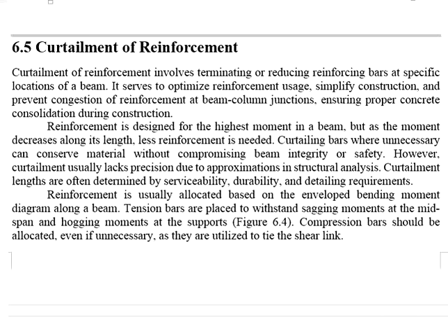Also, you need to know that the curtailment is not a really precise process, which is inherited from the approximations during the structural analysis. You know, in the calculations of the loading acting on a beam or a slab, we do approximations in terms of the design Gk and Qk. Also, we are taught the factor of safety 1.35 and 1.5 for Gk and Qk respectively.